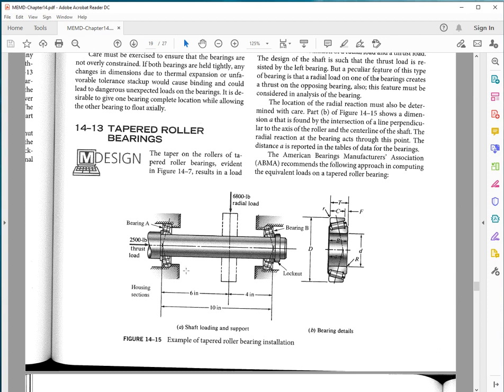So as shown here, this is the O arrangement. If I mirror both bearings, I cannot mirror just one. I need to mirror both, because I need a possibility of adjusting to near zero clearance the 2 bearings. But if I mirror both of them, I get what is called the X arrangement. The O arrangement is much stiffer in terms of angular stiffness. The X arrangement is less stiff because of the apparent reduction in distance between the reaction points.